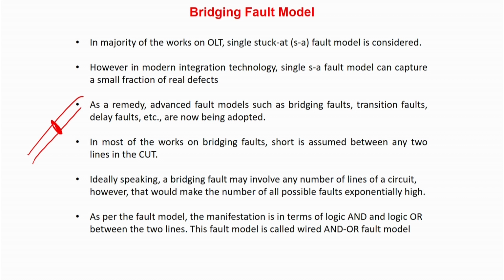But again, as it is a fault model, you cannot always assume that two lines will be neatly stuck and you are going to get a short, and that is the real fault which you have to validate. Real defects can be extremely different. It may be that n number of lines might have got stuck at a point. Or the lines have not exactly stuck, but there is a lot of electromagnetic interference, in which case signals get coupled and the value of one signal dominates over the others and vice versa. The motivation is that in bridging faults you take two or more lines at a time. In stuck-at you take only one line at a time, and in bridging faults you take multiple lines to be coupled in a fault.